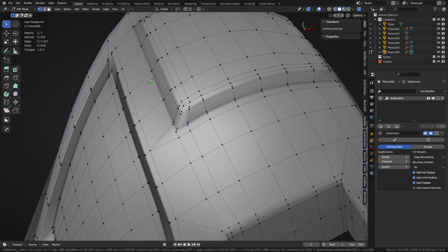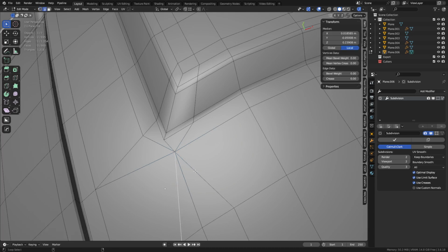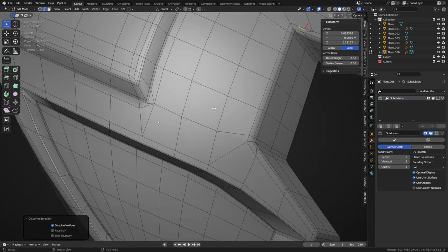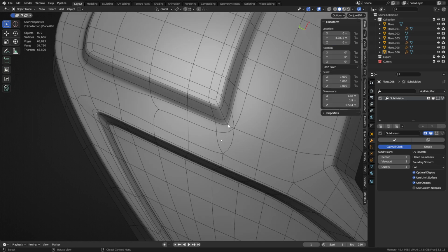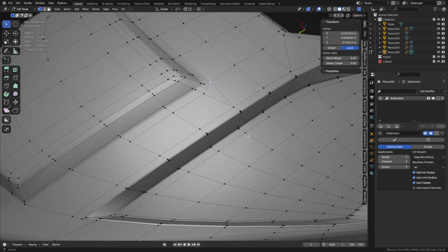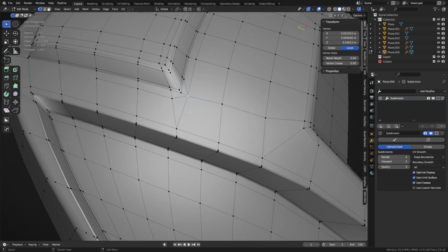If we could, try to knife cut this back out, but sometimes you want to run all your edge loops first before you start trying to merge things together. And in our case here, when we merge these together, we get this kind of a result. You see, so it still works technically, but it's a little bit of a process. And so we can balance that differently. It might eat into the corner a little bit, but sometimes, you know, subdivision's hard to get exactly perfect all the time. So, you know, you got to make the best of what you got anyways.